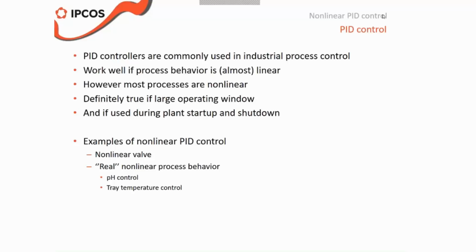The last reason, and definitely not the least, is that proper PID control in the DCS minimizes disturbance propagation. What does that mean? If I have a carefully designed control scheme in the DCS and the PID controllers have proper tuning, then if the process is hit by a disturbance, the PID controllers and the control scheme in the DCS try to keep it local. So that means the disturbance doesn't propagate upstream or maybe downstream.